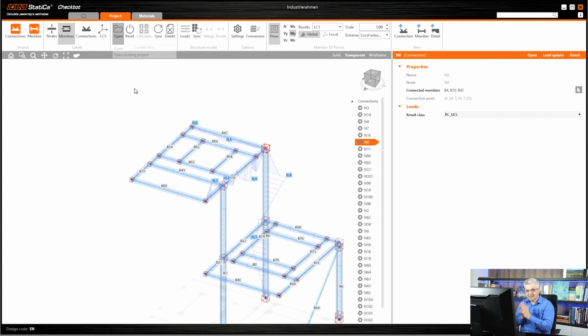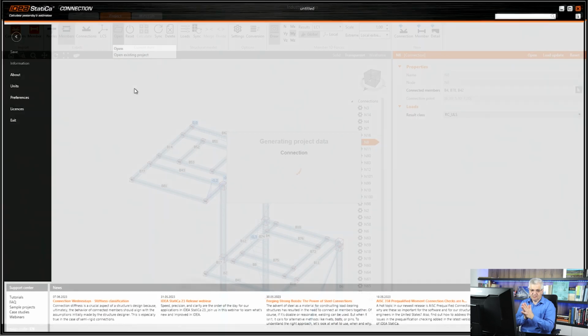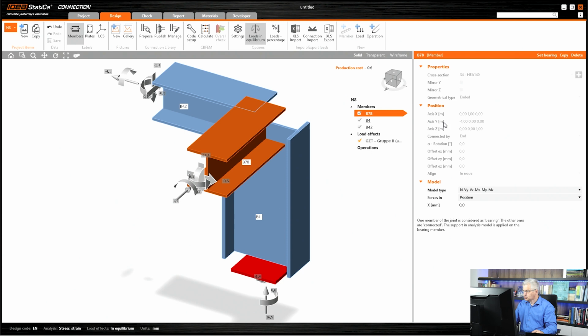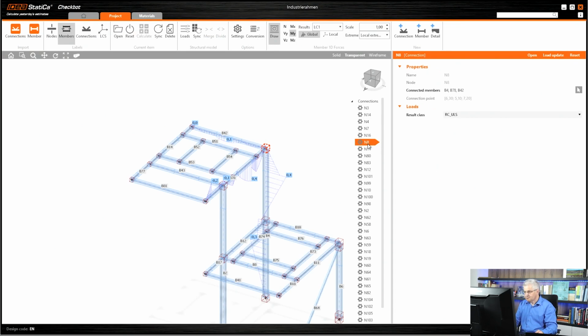And then some of the geometry of the members is blocked, we will see it. You cannot change it. It's because of the synchronization, and developers cannot allow everything to the users, because then the synchronization would not work. But if you need to change something, then you can simply click with the right mouse button on your node and go to export to separate files or single project.